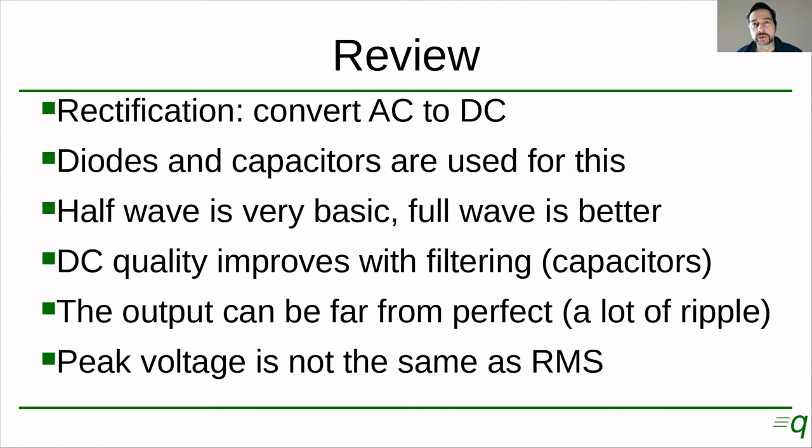And finally, we also saw that peak voltage is not the same as RMS voltage in AC. And this is very important when we use rectifiers because the DC voltage of the rectifier is going to be closer to the peak voltage and not to the RMS voltage of the original AC voltage.